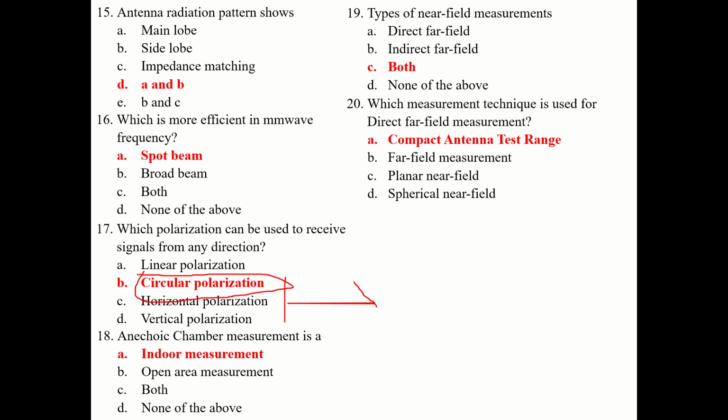It is not planar near field or spherical near field, because there a transformation is needed. So the answer is compact antenna test range.